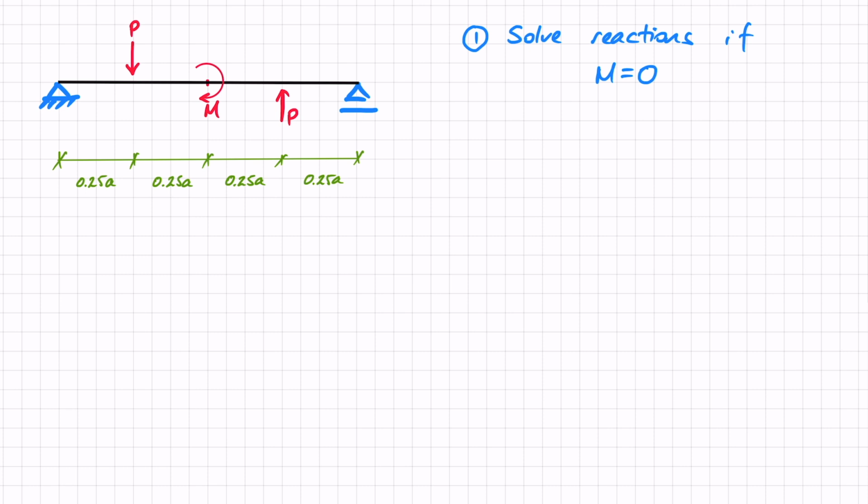So, as I mentioned, the first exercise has this beam here. Let's call this A and B. And as you can see, we've got these 2 point loads, P and P. They are equal in value, but opposite in direction, and they have a distance between them. That means they give us a coupled force, which means that the moment they produce is equal everywhere. Now, in our first case, this moment is 0. So just so we don't get confused, I'm going to delete it quickly. There we go. No moment there. Let's solve the reactions together.